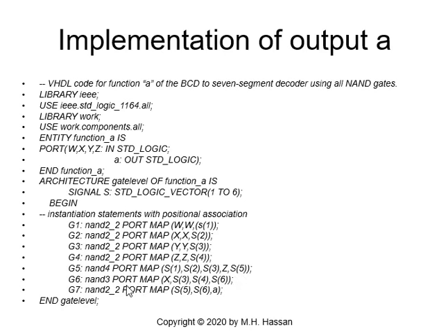In the 3-input AND gate, the port map is X, S3, S4, and the output is S6. In the last NAND gate, which is G7, a 2-input NAND gate, I have S5, S6, and the output is A. And this is what I'm looking for. And I will end the gate level, and by this we implemented A.